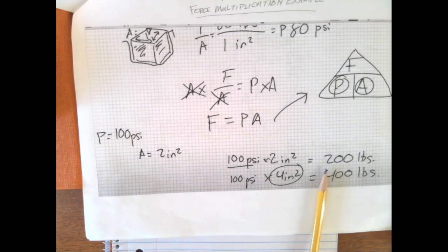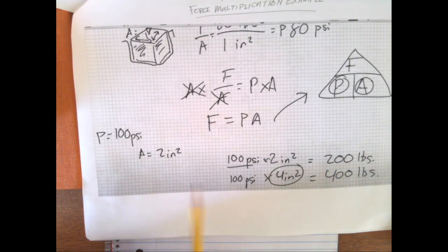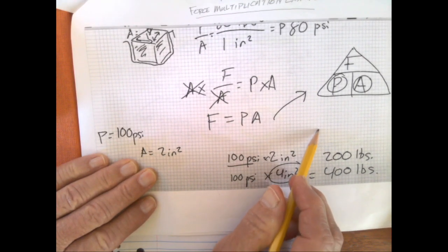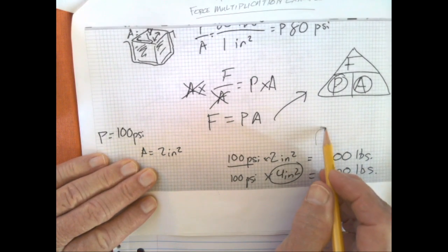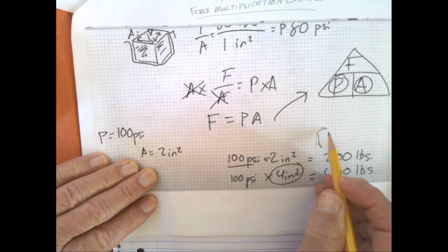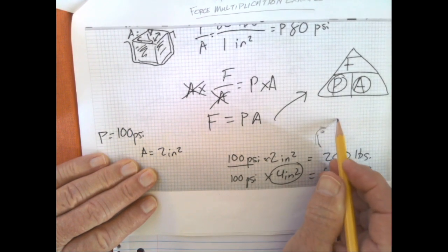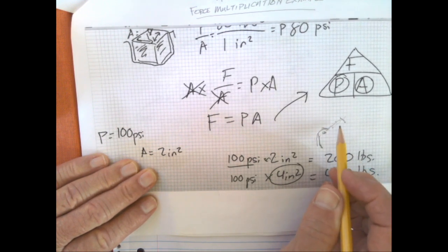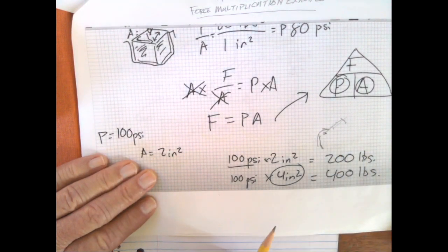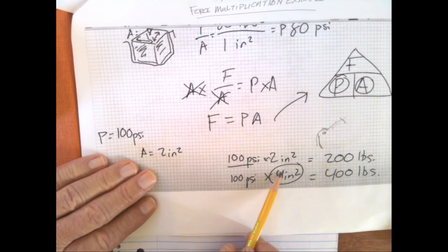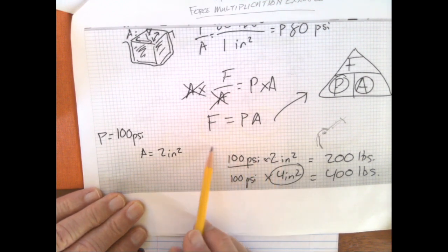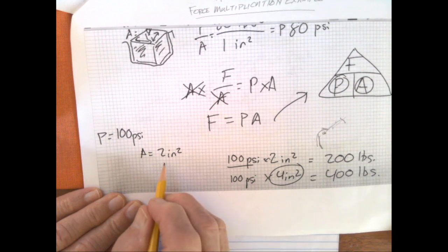Again, we'll get into this. You're going to lose a little distance in your actuator. Let's say when that bucket is trying to curl and that ram is coming down here, you're going to lose a little distance and maybe a little speed. In this case, you'll lose half the distance, because you want to remember these factors.